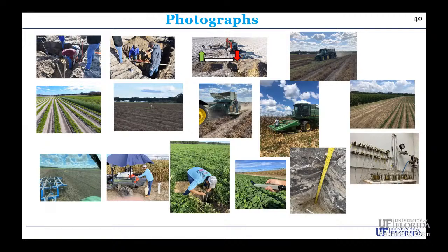it was very strategically installed in such a way that the data collection systems, where we collect all samples, are in alleyways, so there is no tractor movement on that, so there is no compaction issues and so on. And we install in such a way that some of the lysimeters are directly underneath the crop, and some of the lysimeters are like 30 centimeters away in between the two cropping rows. So that requires very much precision in installing those.